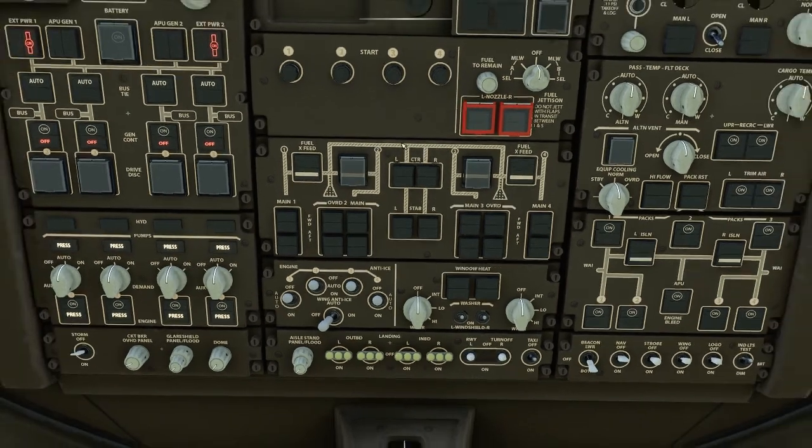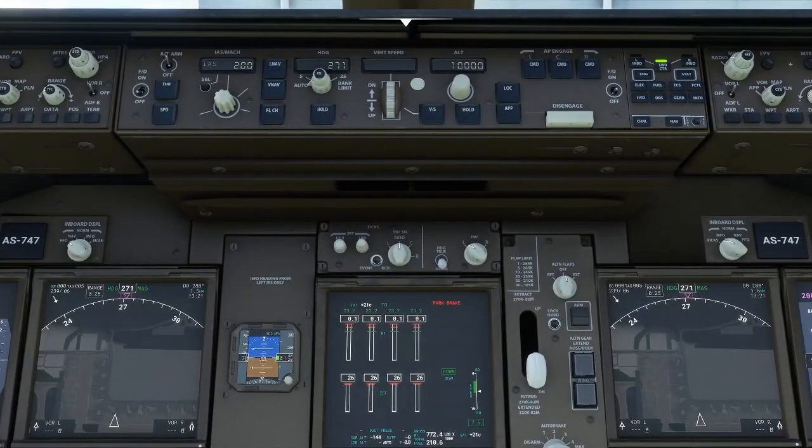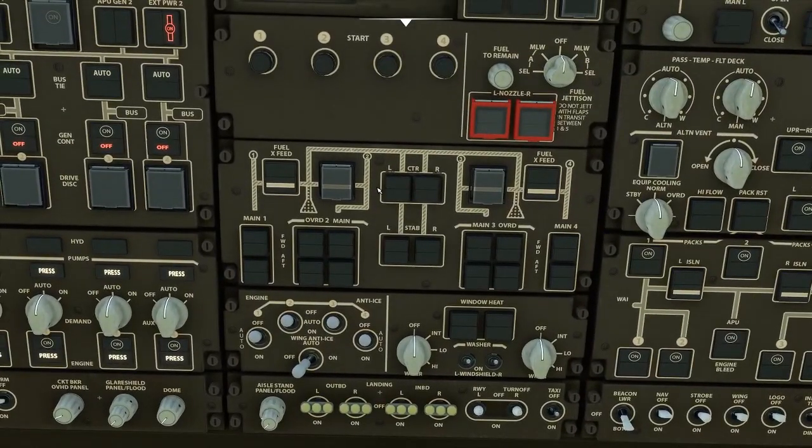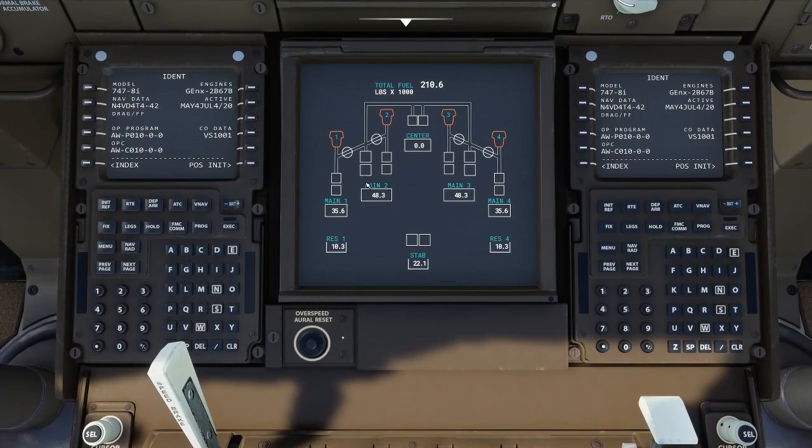This is one of the few synoptics on the lower ICAS that's actually working. So let's see if we can get it up. So there's lower ICAS, and as you can see, we've got, this is in pounds of fuel, which is a bit weird for me. So I'm normally used to flying in kilos, which I think most of you probably use. And so you can see you've got engine 1, 2, 3, 4, and then all these little white boxes are all fuel pumps.